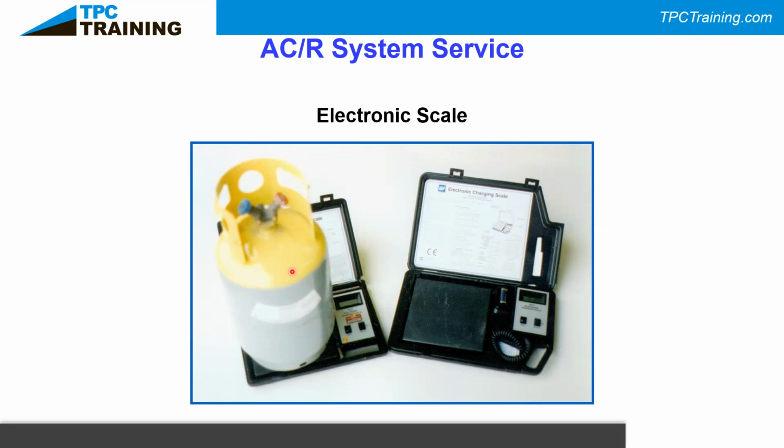So your box temperature is 38, or freezer minus 10 degrees. For air conditioning, it's generally going to be R22 and R410 that are your more popular ones out there. This cylinder is meant to take the refrigerant out and store it in our cylinder until you need it. Now, it's not meant to go back into somebody else's unit. It's only meant to go back into your unit or a unit that you own. So if there's anyone on this call that works for an apartment complex, you might have 50 different condensing units and 50 different air conditioning systems in your apartment complex.